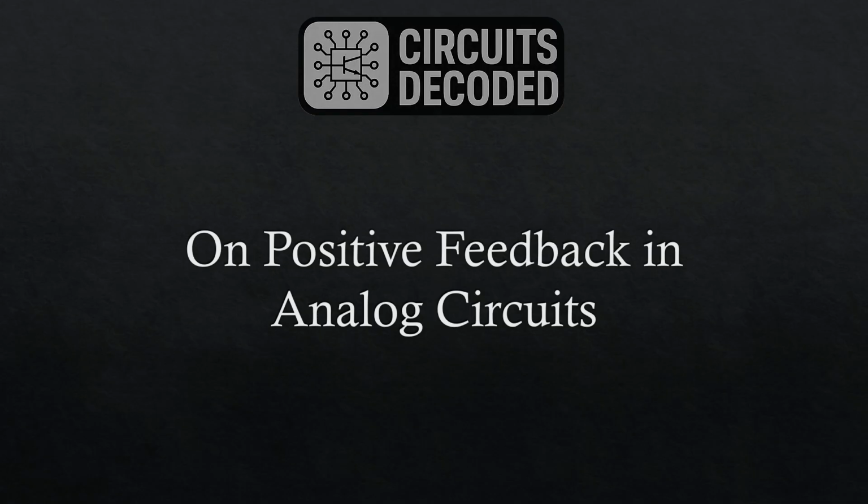Today I want to talk about a few analog circuits with positive feedback and discuss their stability. So as analog engineers, we are often alarmed at the sound of positive feedback as it relates to instability. But at the same time, we are comfortable with circuits like oscillators and latches that work on the principle of positive feedback. Likewise, there are several circuits in the analog domain which also have positive feedback in them, but we don't quite notice the positive feedback at the first glance.